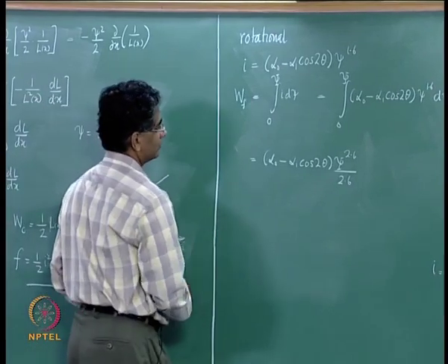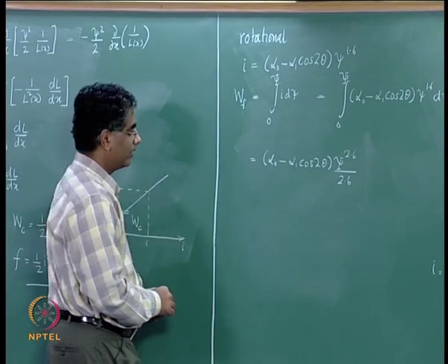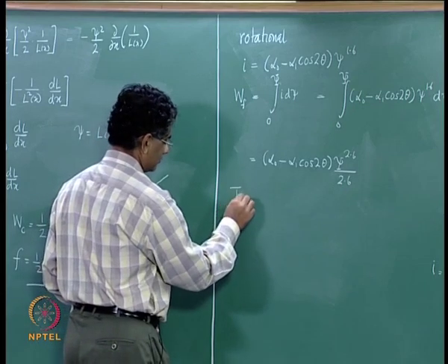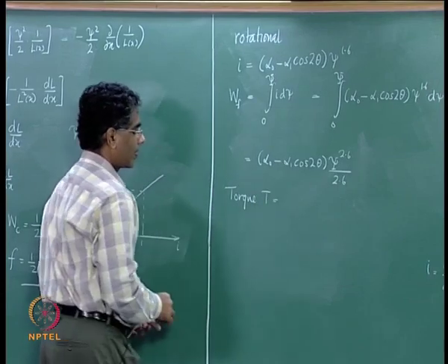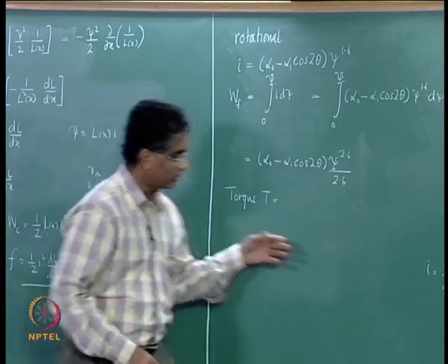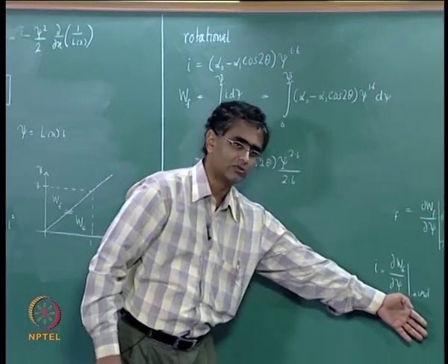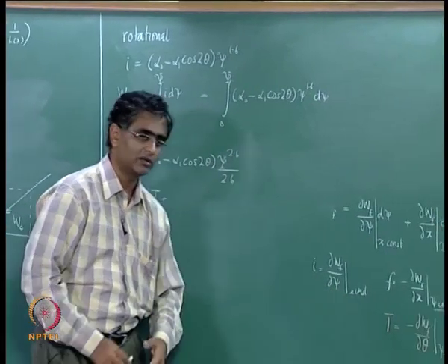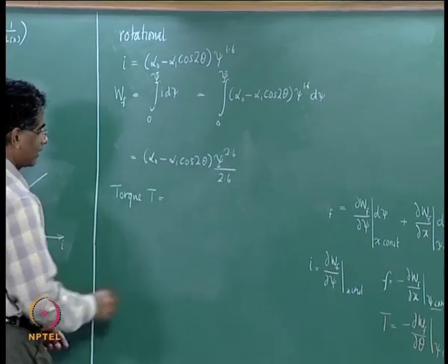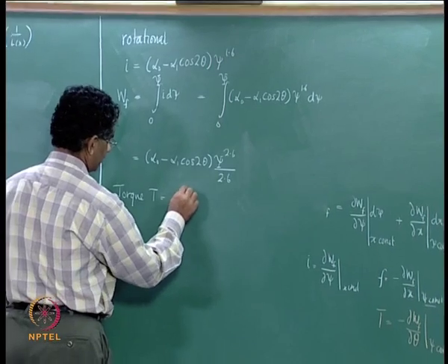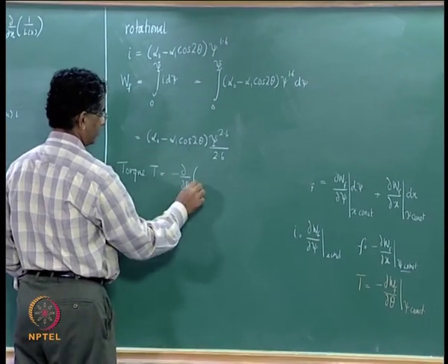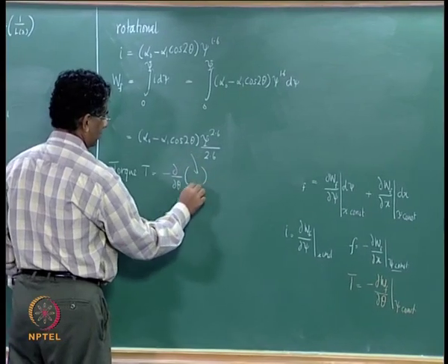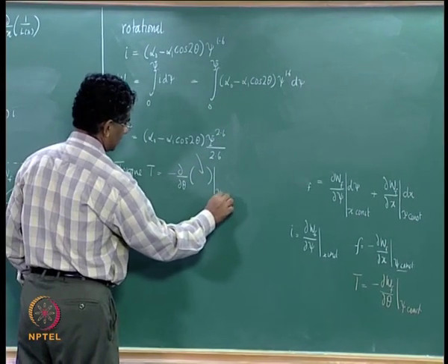In this case what we are interested in determining is the torque T, and the torque T is given by minus of dou Wf by dou theta, keeping psi constant. So this is minus of dou by dou theta of this expression, keeping psi constant.